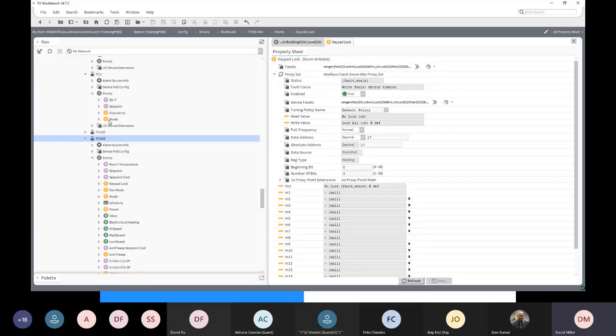Okay, and typically on a Modbus project or a Modbus network, you'll have many devices all with the same mapping table. So you'll have 20 power meters, all the same with the same mapping table. And from an estimating point of view, if a project says we've got a Modbus trunk, the question to ask is, what's on that trunk?